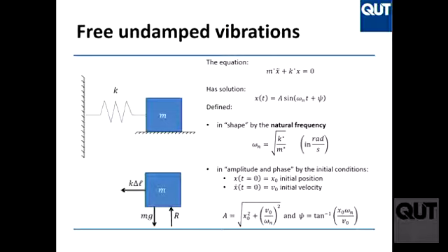That's one of the problems. Of course, fatigue on the shaft will develop some crack in the shaft, so it's bad for the stress. But even earlier, if it vibrates too much, what happens? It touches. It rubs. Imagine your blades are rotating within a certain gap that's left there, right? If this thing shakes like crazy, these blades are going to hit the stator part. So vibrations in turbines are studied a lot for this reason, because there are very tiny tolerances for fluid dynamic